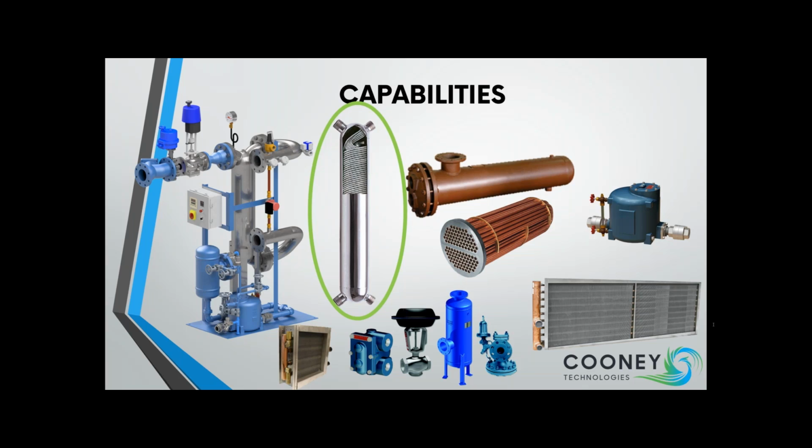So we can oversize this to make this a subcooling unit. As your cold water comes in, it's picking up the sensible heat from the condensate in the shell and coil tubing. Then it picks up the latent heat as it gets up higher in the heat exchanger and exits through the top left out to the system, whether you're running 120, 140 degree water.